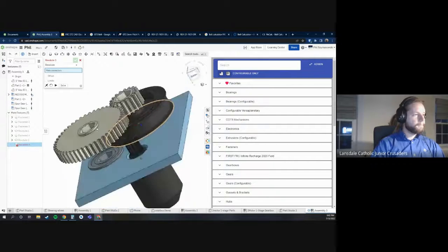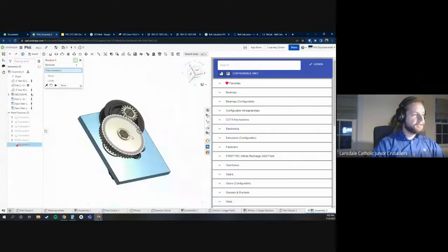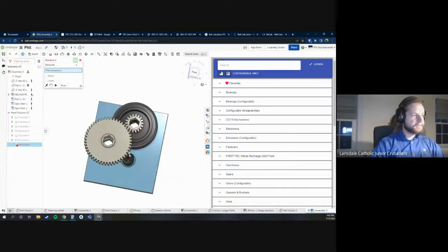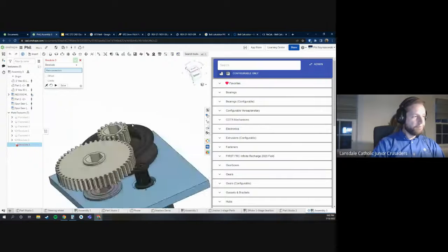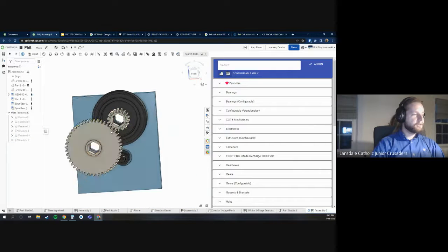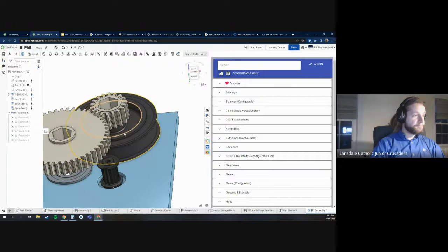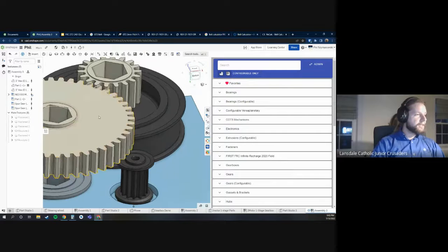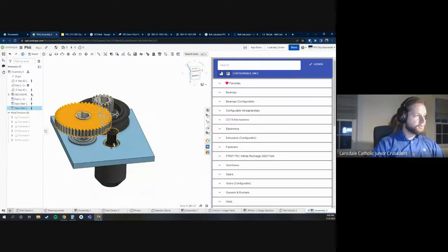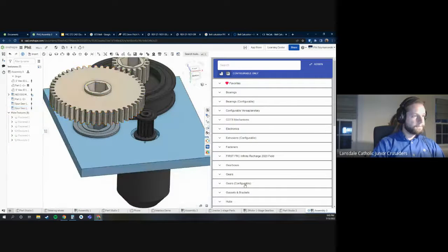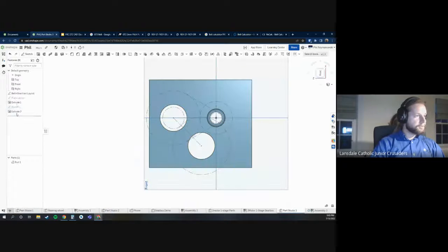There we go. And so now you could see, if I put shafts in here, and if I put a plate on the opposite side, and if we put some standoffs in here, we have a really, really, really compact design for a 2-stage reduction gearbox. And it's pretty light too, because in our first reduction, we have a pulley instead of gears. And it looks like I could even bring this gear closer to the motor if I wanted to, because the bearing doesn't run into this pulley. So I'm going to do just that.